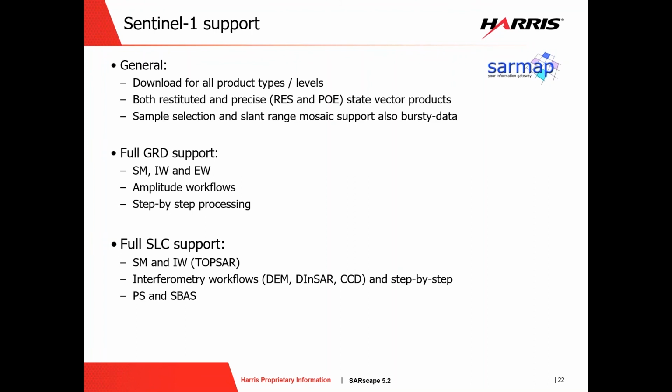This engine to support the interferometric processing of Sentinel data flows into all the interferometric processing modules. This means workflows for DEM generation, displacement maps generation, coherent change detection, both in the workflows and in the step-by-step processing. But very interesting, this engine allows you to perform interferometric stacking processing of several Sentinel-1 acquisitions to perform persistent scatterer processing and/or small baseline SBAS processing. So all the interferometric modules have been updated to handle interferometric processing of TOPSAR data.